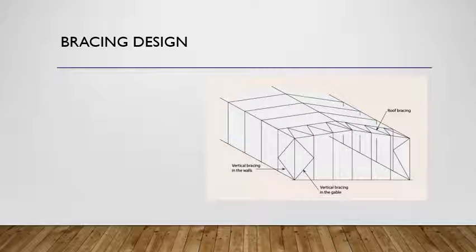The next structure we need to design is the bracing design. In construction, bracing is a system to reinforce the building structure in which diagonal supports intersect. The bracing can increase the building's capacity to withstand side loading activity. The vertical bracing, which means the bracing in the vertical plane, will provide the load path to transfer the horizontal force to ground level and provide lateral stability.